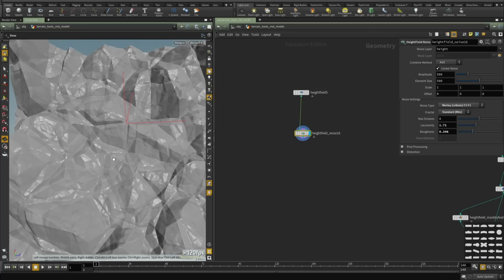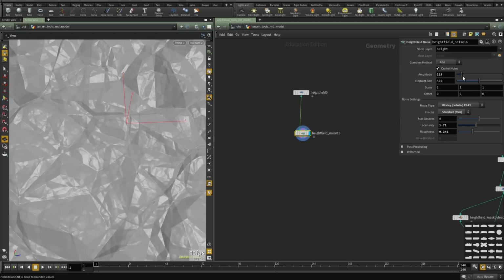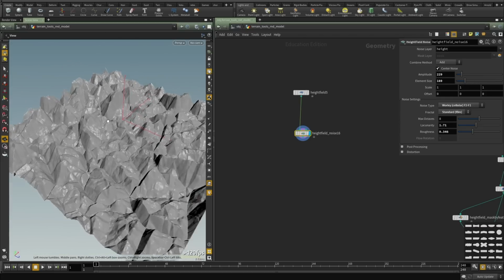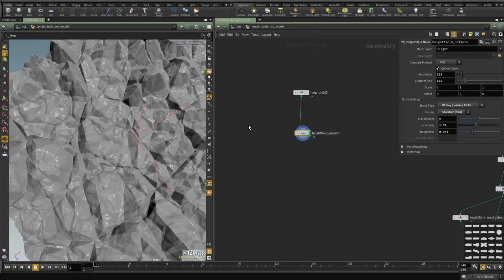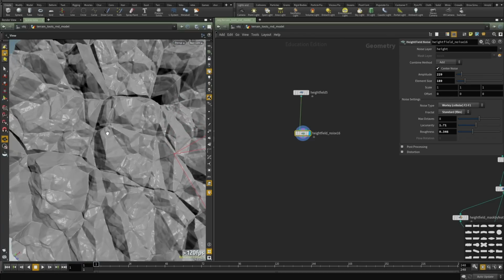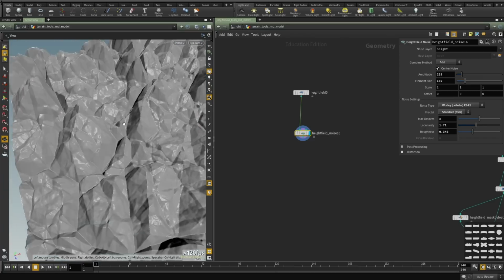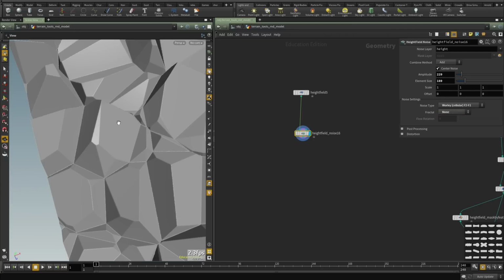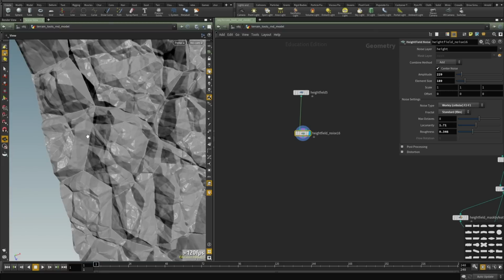Roughness. And let's reduce the size, the amplitude, sorry, and the size as well. So something like that. And what I like about this is we start getting more breakups into these instead of just this, we get an iteration, a second iteration and a third iteration trying to break this Worley with a similar pattern. You can see some very interesting cracks.